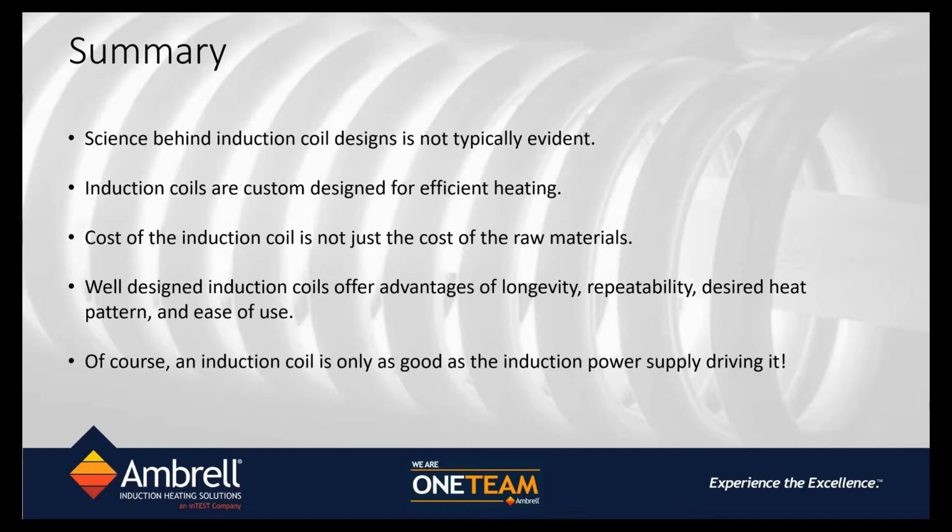All right, and our next question is, can you suggest any material which could be used to fix two pieces together when brazing? We are brazing carbides to steel bodies and need something which would keep the carbide in place while we heat to 2000 degrees Fahrenheit. This implies to me it needs to be something which is not easily heated by induction and which has a high thermal resistance. Ideally, they would be reusable. I saw ceramic as an option in your presentation, but I fear the manufacturability of that is insufficient for our usage.